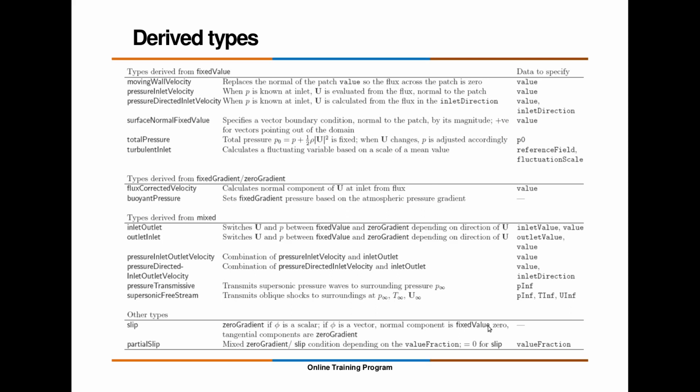Let's say we are talking about flow through a channel, and we talk about the slip condition on the top wall. The normal component on that particular top wall is the y component, so y equals 0, and the tangential component with the top wall is the u component, so the gradient of the u component goes as 0 if it is 2D.